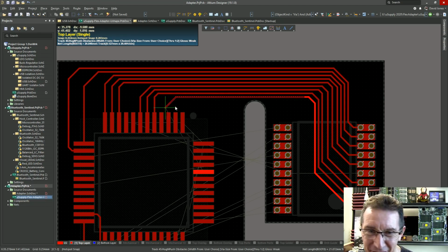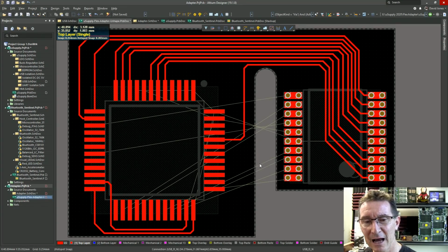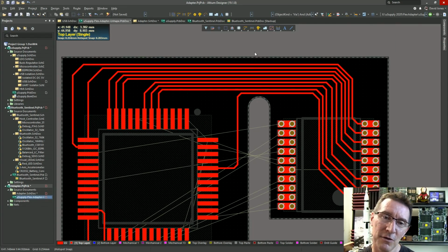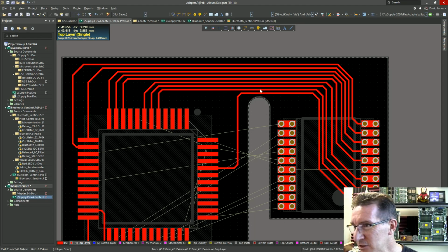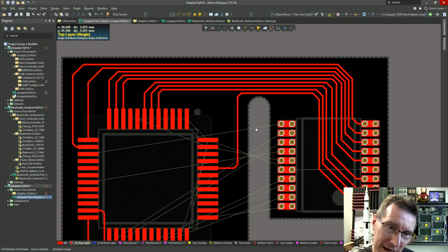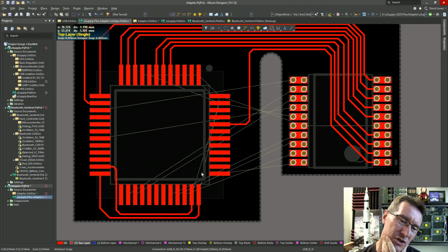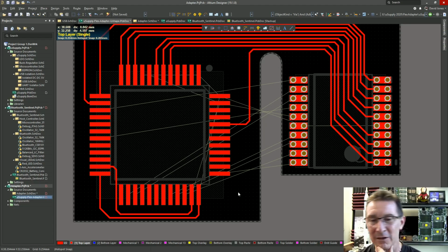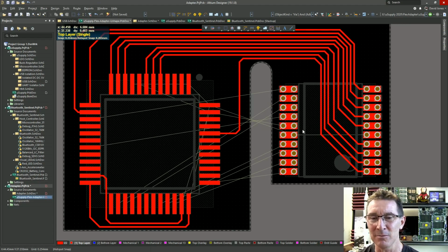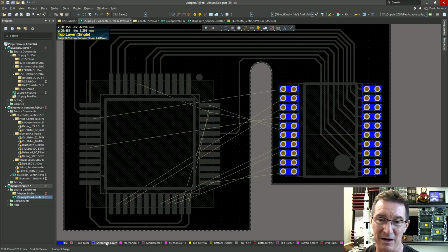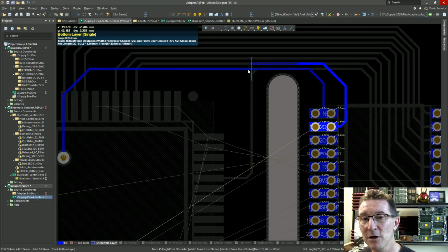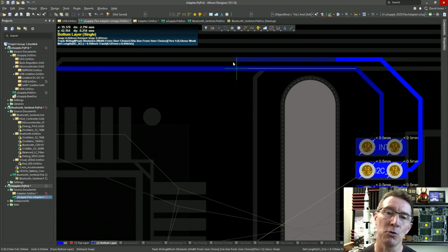Oh, why can't they go to there? Now, you could argue that I can maybe increase the width of this, for example, because I had that available, and then route some extra traces around here like this from here. But really, when you look at this, these ones have to go over to here anyway. Then they're going to have that same routing squeeze constraint that I had through there before, and there's 3 of them, and, look, couldn't be bothered. I'll just route all these out on the bottom layer. By the way, sometimes when you're routing traces like this, often you will offset them.